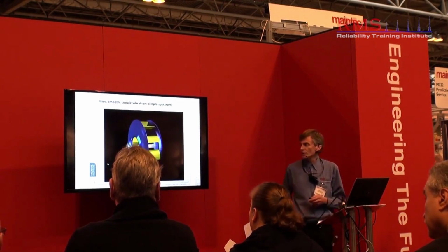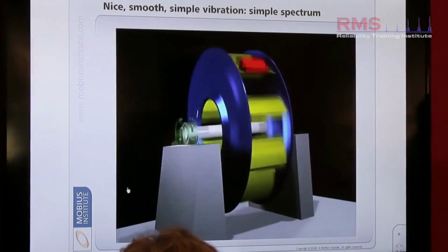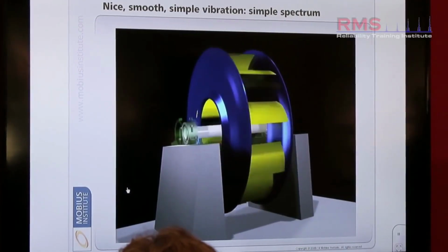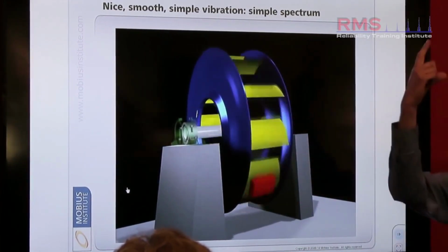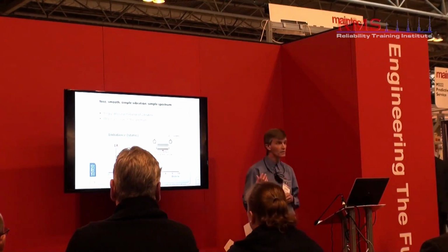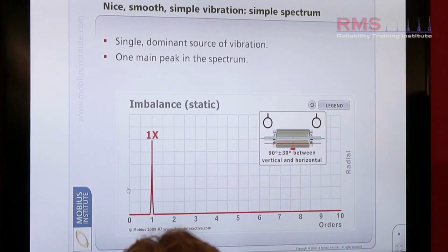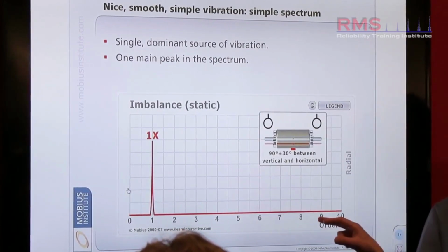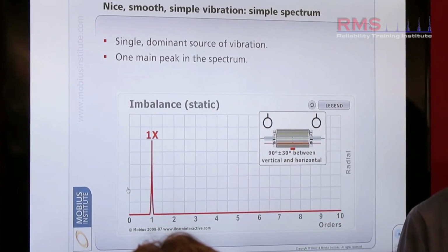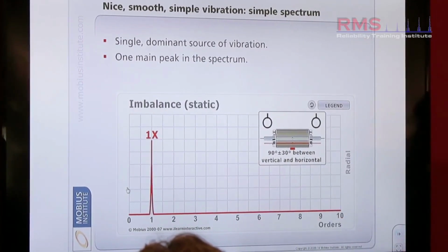So where the vibration is smooth, in summary, what do we see? A heavy mass rotating around the rotor, a strong radial force, an increase in vibration at what frequency? Once times the speed. So an unbalance in a system will actually occur at once times the speed. Little else present, that's the main problem. Other peaks might mean there's a second problem.